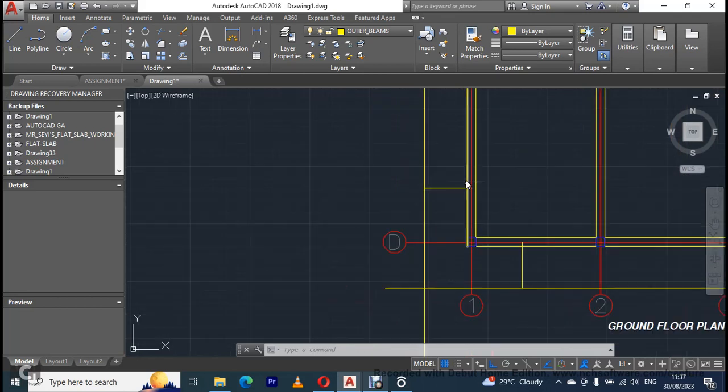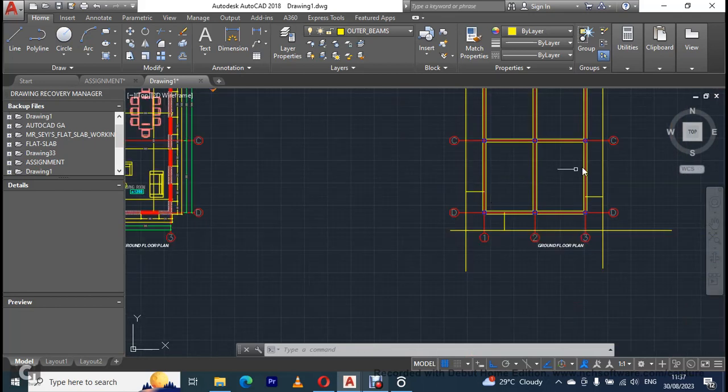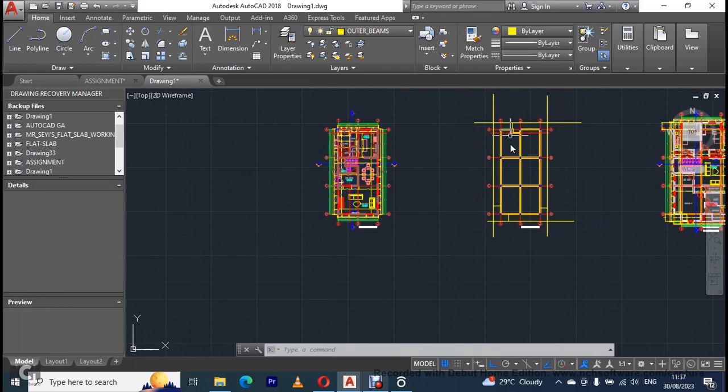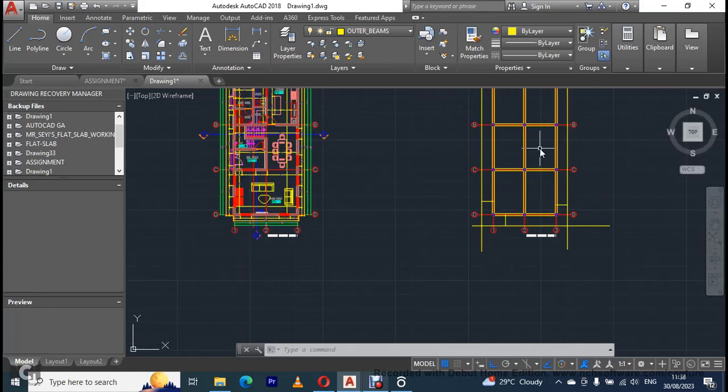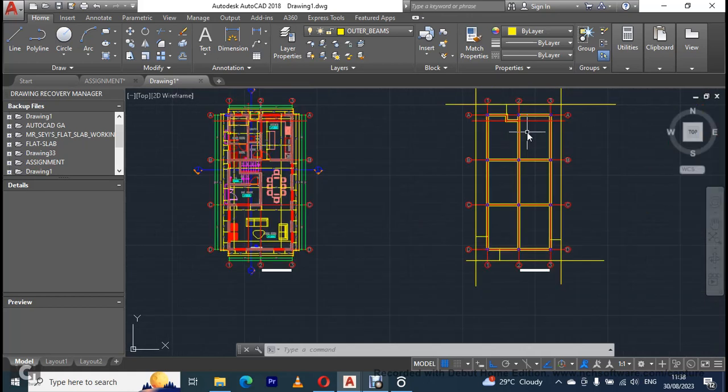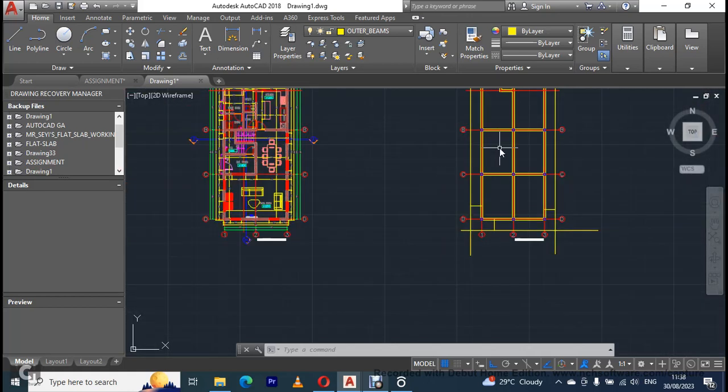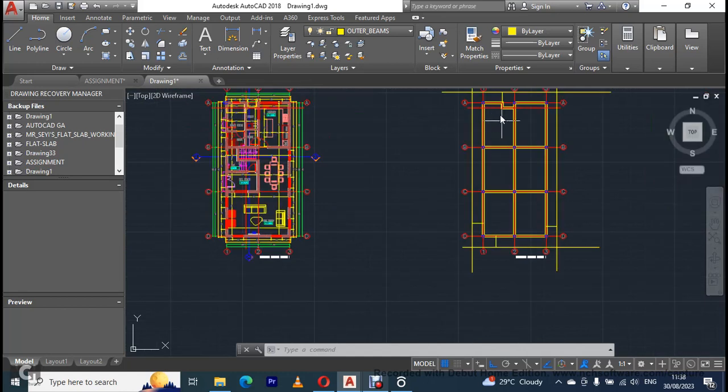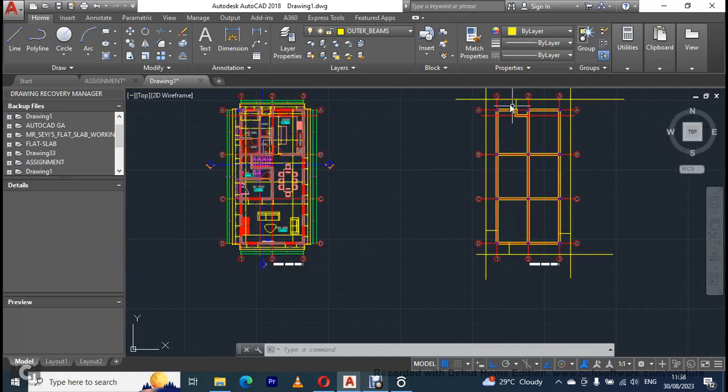Since these two beams are all connected to slab, there's a slab here, there's a slab here on this panel. So everything around here is a bay. The combination of all these panels is the bay. So this is the bay along the y-axis, and this is the bay along the x-axis. Very essential. Each of them are called panels, and they are most likely going to be two-way slabs, meaning that all four edges of the beams are carrying the load of the slab, the load imposed on the slabs.